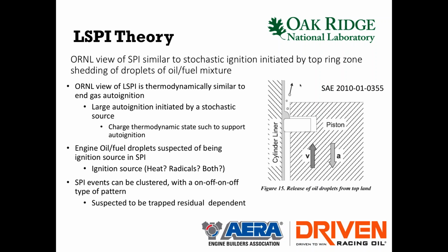But there's a definite theory of the droplets released, and there's a lot of validity to it. We know there have been cases where changing the piston design or the ring package can greatly reduce, and sometimes even eliminate, LSPI. But typically when you're doing those kinds of changes, you're also hurting fuel economy because you're increasing friction and changing the oil control to some degree.